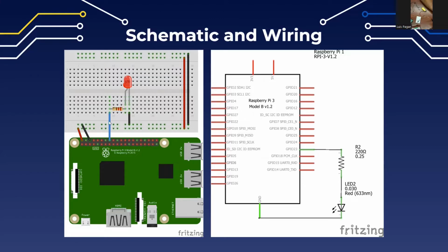So we're going to wire it, connect it to the resistor in series. We're going to make sure all of this is in series. So the signal is going to the resistor, which goes into the LED, which again, they're on different rows, so they're not connected to each other. And then you're going to connect it to ground to make sure that there's a voltage difference.